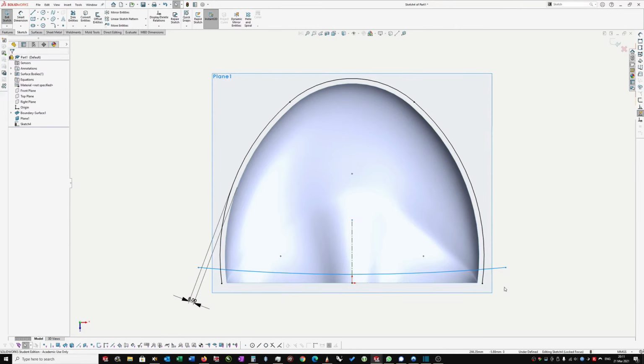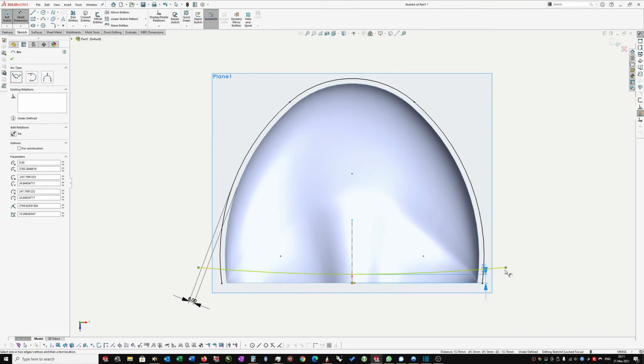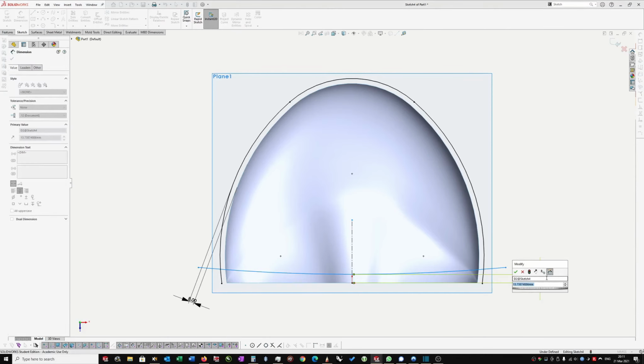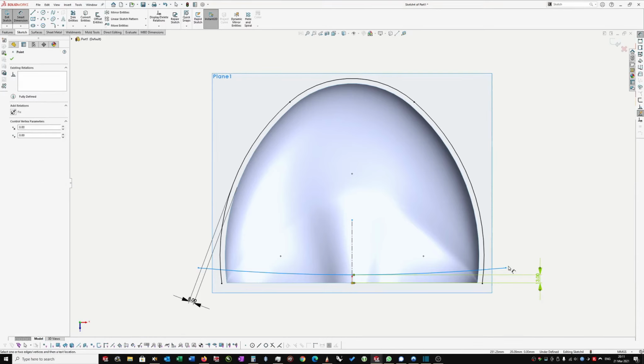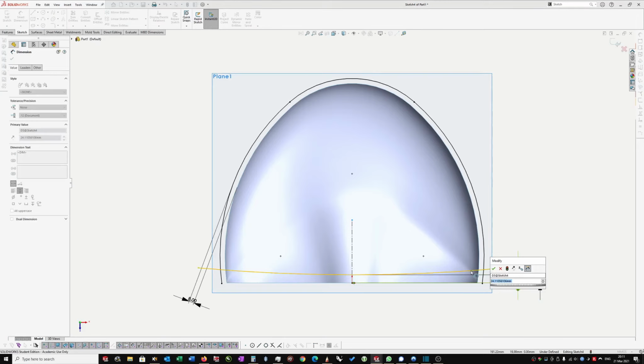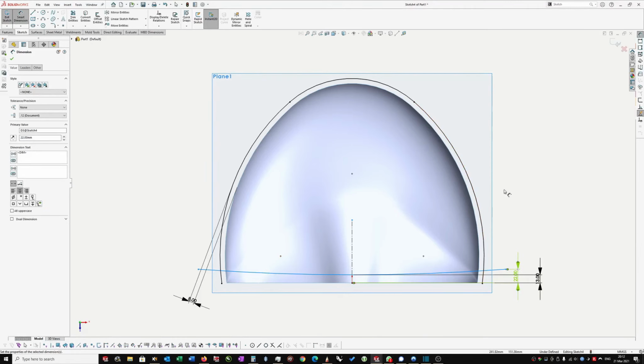There we go. And I'm going to hold the shift button down and make sure that there is, so about 13 should be okay. And I want to control the end of this curve, which I could actually control how this curve looks by putting a radius in, but this is probably just easier for now.